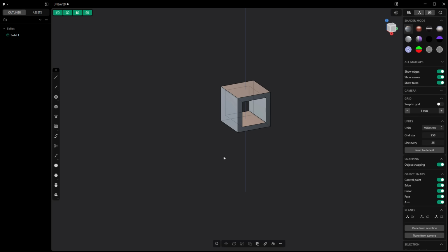So there'll be one tool that can do multiple things. And in other cases, commands like selecting a face and hitting delete on the keyboard or hitting X on the keyboard, sometimes those things will actually allow us to do the same thing. Now, in other cases, you may actually need to use a combination like Shift and X if you're trying to delete a face from a solid body, whereas if you have a set of surfaces or sheets, you can just hit X to delete it without having to worry about it trying to patch it.